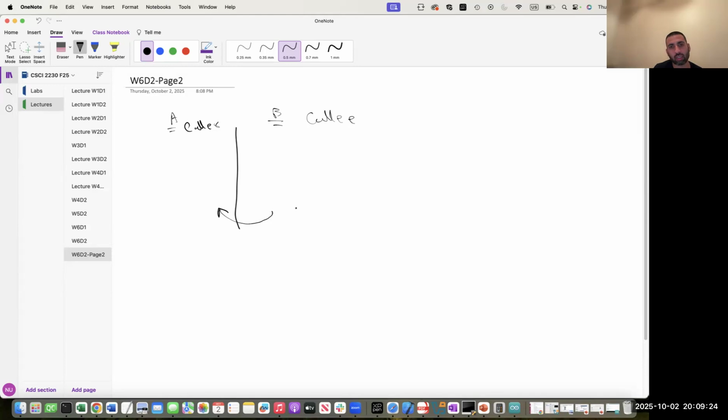It can return the values by using 8 registers, R25 down to R18. What you do is put the first value which you want to return, let's say A, in R25. The second value which you want to return, let's say B, you put in R24 and so on, and then you call return.